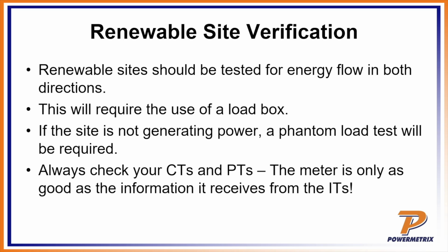So in summary, with the renewable sites, first rule is that you should test for energy flow in both directions. Make sure that it's working both positive and negative. Now, of course, most folks aren't going to stick around till nighttime to test the meter. So an easy way to do that is, of course, use a load box. Most modern load boxes can be programmed so that they can look like delivered or received loads, and so that makes it very easy for the meterman to be able to check that.